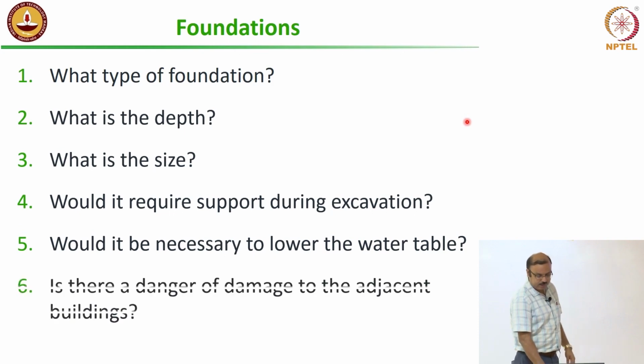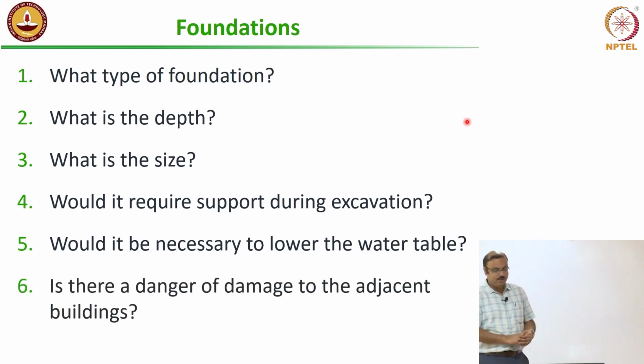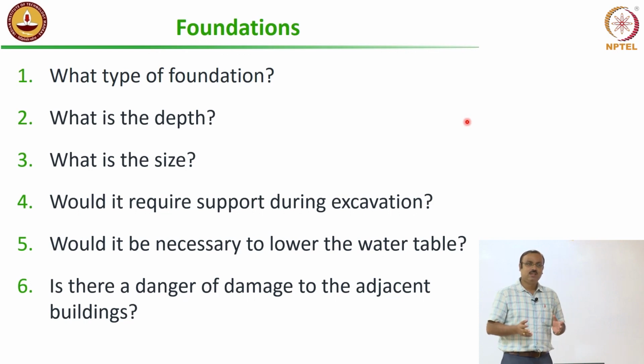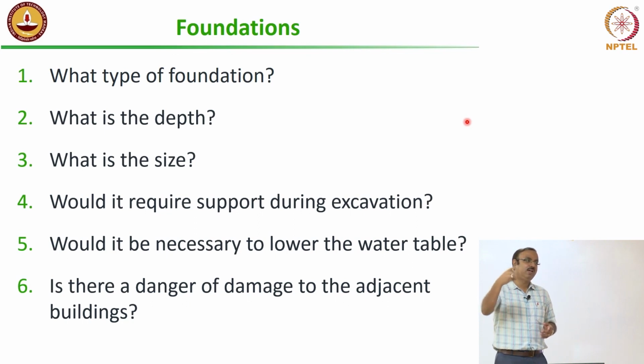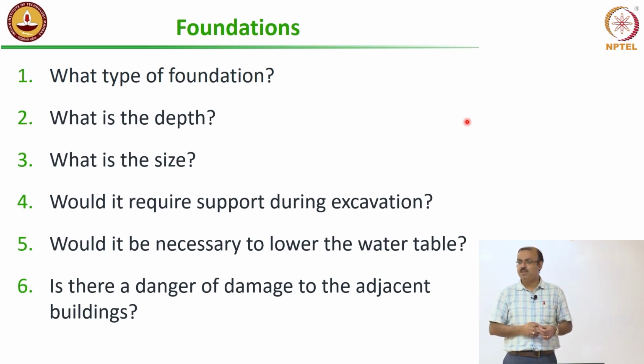So whether it is necessary to do that, and whether there is a danger of damage to the adjacent buildings. With all these work activities, are you disturbing the nearby structures or the residents? You may have piles, like you have seen in the foundation. When a pile is getting installed, there is a method where you have to drive it, so there may be noise coming to the building. Nearby residents may complain that it is like a hammering sound, day and night there will be hammering. So these are the practical challenges a geotechnical engineer also has to face.